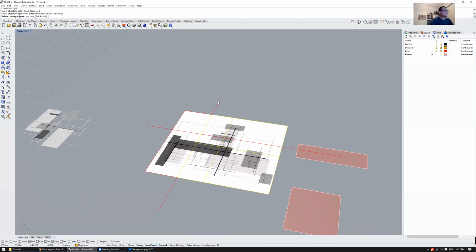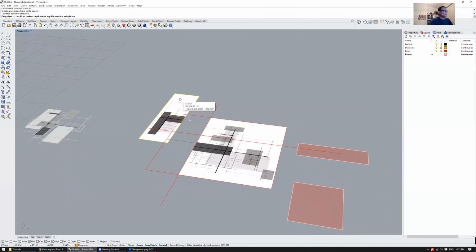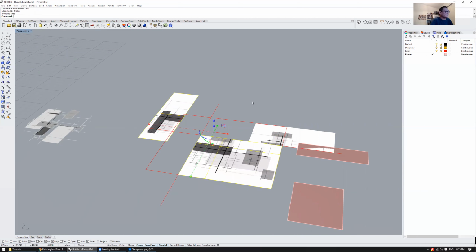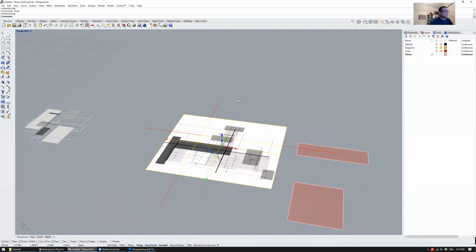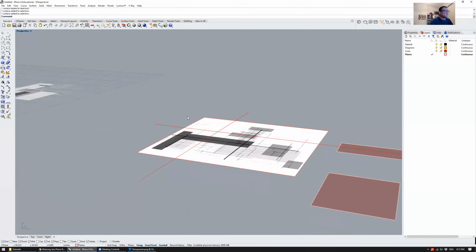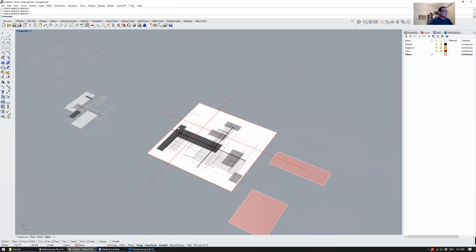Cutting objects, both of these lines, enter. What that does is it splits it right over there. I'm actually not sure why it didn't split the very end over there, but you could do it separately if you wanted to. In this case, at least it's split into three different parts. That might mean that that line isn't exactly on the XY plane.